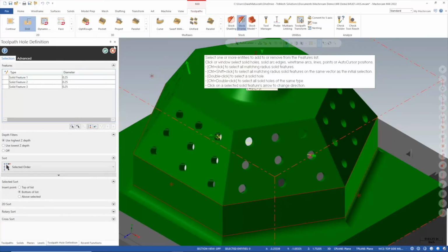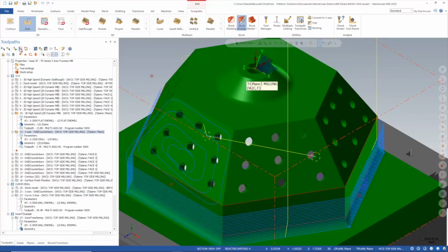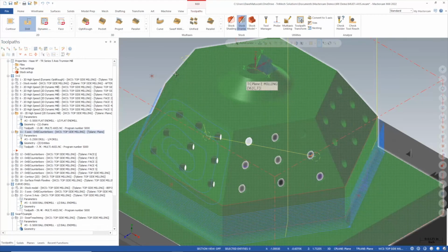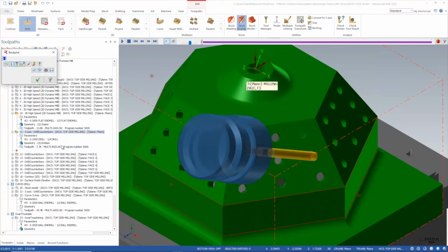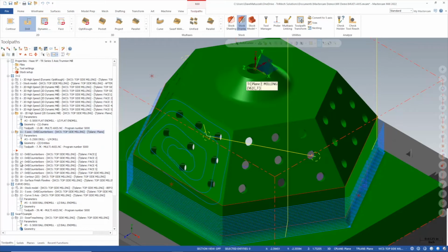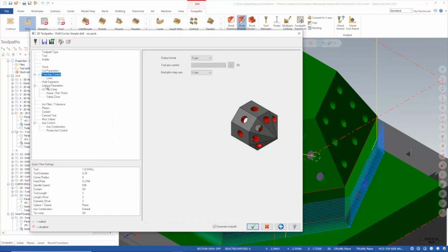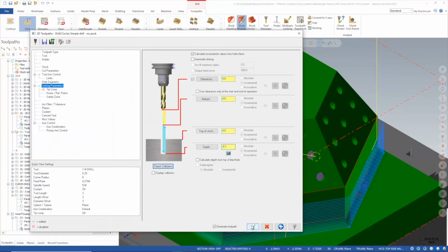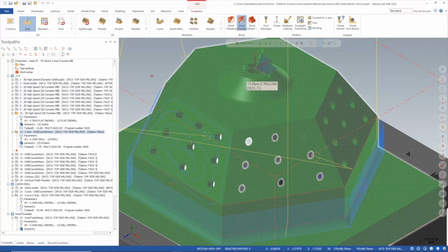So if something like that happens, you never have to panic in Mastercam. You can just go back in and say, man, I had an axis going the wrong way. We'll click on it. We'll change it. That looks better. I know I don't have enough reach there. Again, it showed me that right off the bat. We don't want that to happen, but it's visual. Again, everything Mastercam does is visual, and I can come in here and just know that, hey, I really need to give it a bigger clearance height. Now I know I can clear that part before I index around.